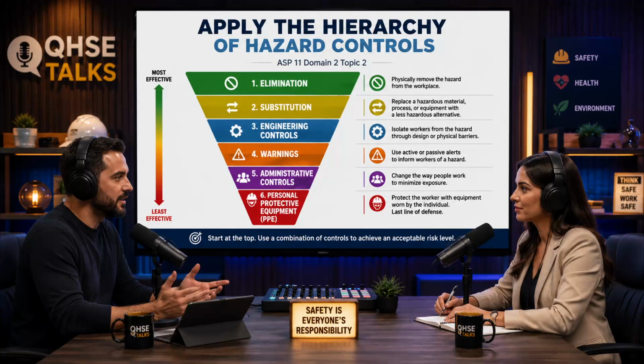Okay, so once you have that specific scope locked in, what is step 2? Step 2 is identifying the potential hazards. This is where you catalog the physical realities. Like the chemicals being used. Right, the chemicals, the kinetic energy of the machinery, the thermal energy of a furnace, maybe the biological hazards if you're in a lab. You're just looking at the raw potential for harm. Exactly. And that leads us directly into step 3, which requires considering the failure modes.